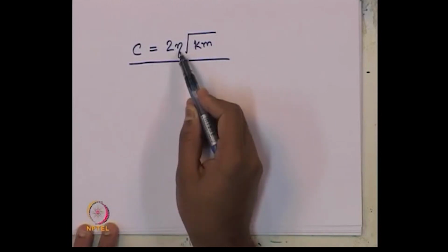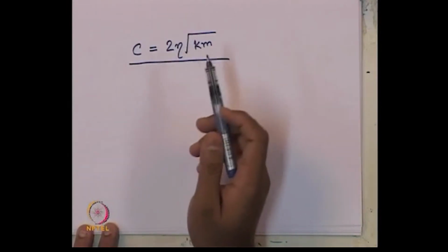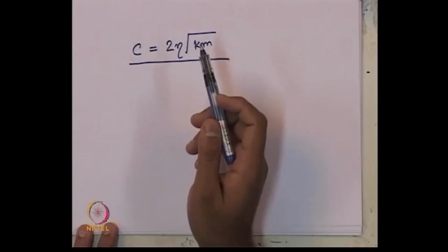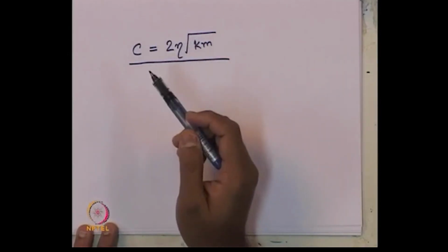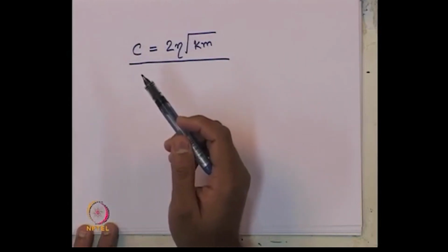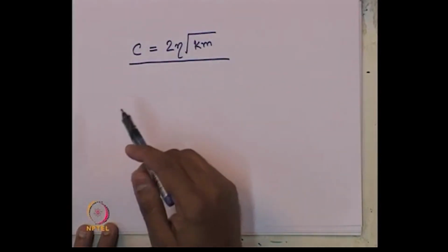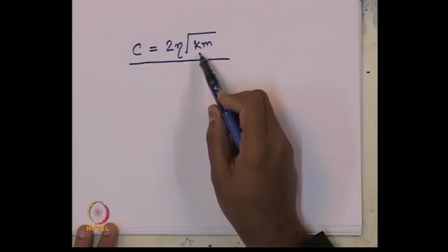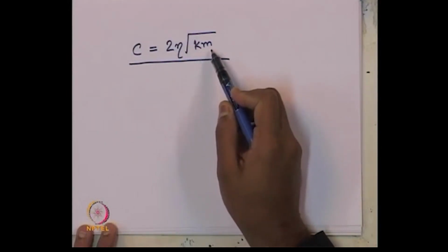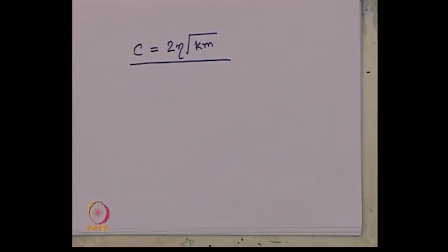Here, the damping ratio of the soil should be known to us; in our analysis we have varied different damping ratios. You can easily get a design chart for different damping ratios or different types of soil. We have considered 5%, 10% and 20% damping ratio, which are the practical ranges for the soil material, as we had discussed earlier also. K1 we have already computed, and M1 we have also calculated. So, we can get C1 very easily.